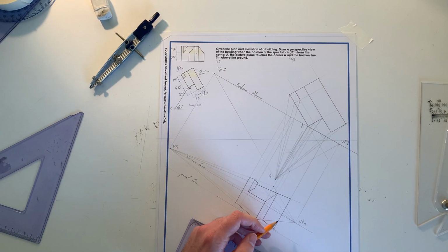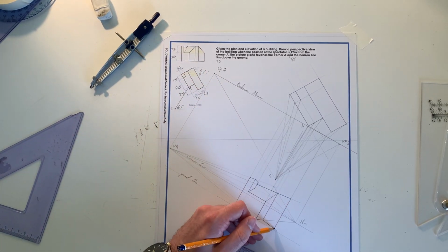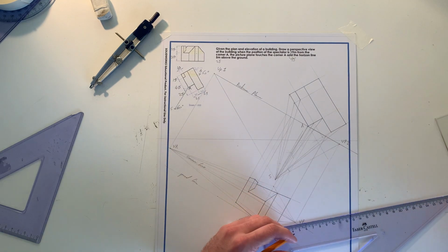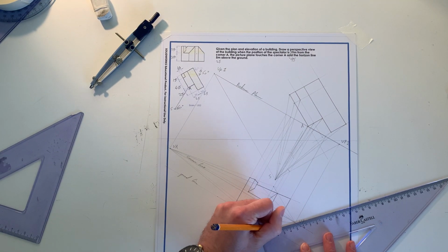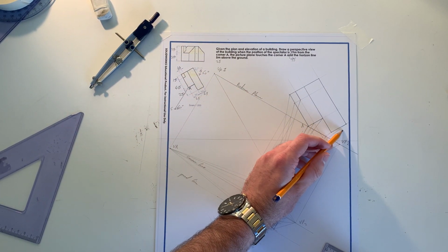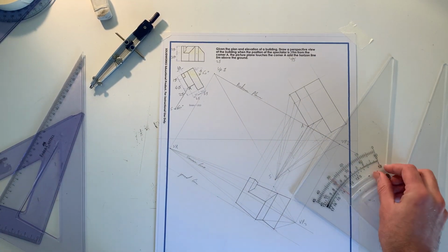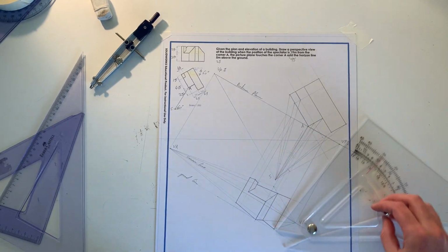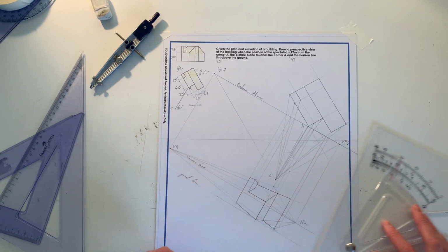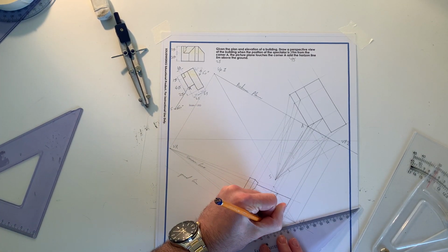And also I know I need to finish this off. I need to find that surface over here. To do that, I know that I can join this point back to my VP2 because it is traveling back to the vanishing point. I know if I want to find this corner over here, I just get in my plan, join it back to my spectator, which I already have, and then I just need to drop it down again. Like so, perpendicular to my picture plane where it intersects, drop it back so I can see it stops there, and now it looks a bit squashed just from the way that we're looking at it in the perspective.